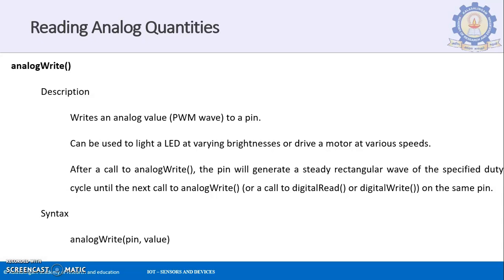But if you want to vary the speed, as in the case of a fan, you can use this analogWrite signal. You cannot use a digitalWrite here; you will have to use analogWrite.